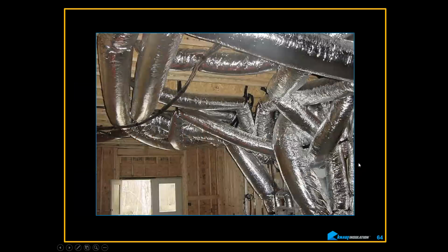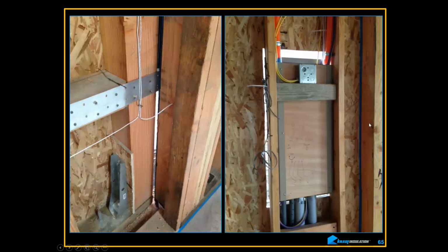And this is what you see. You know, you can't make this stuff up. You just can't. Same house. They have no clue about air barriers and air sealing. So the exterior sheeting was never even completed all the way to the corner. It stopped short of it on both sides. But they do have air sealing down here. Great. That's not really accomplishing anything. I don't know what they're going to do with this.